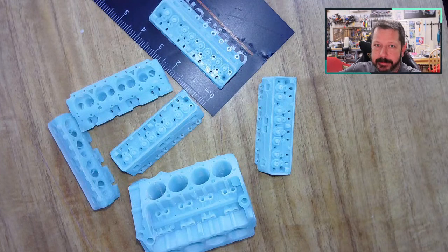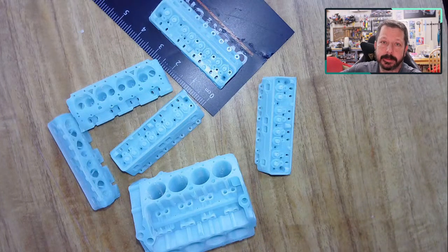It doesn't have to perform quite as expected, because unless you have access to the right kind of printers, it's going to be an FDM printed part, and the solutions don't consider the layer lines of an FDM print as part of the material properties.